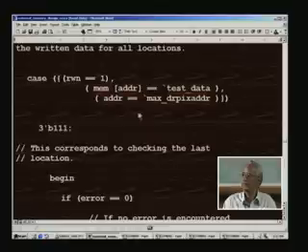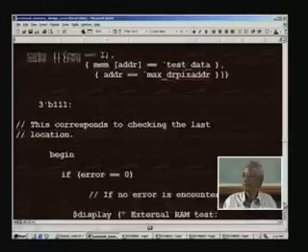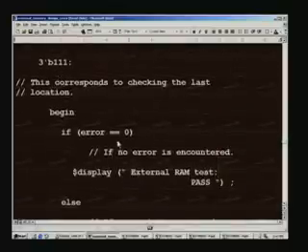That means to say we have already read all the 65,000 locations, and we are right at the tail end of that RAM test, and when this happens what we should do is, we further have one more flag, a signal called error. During the course of writing and checking back every location, it may so happen that one of the locations is faulty, in which case an error flag is set.